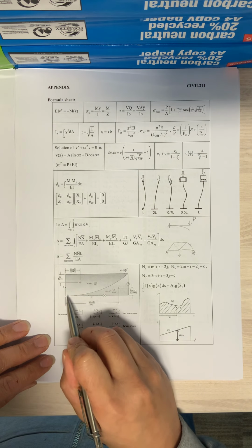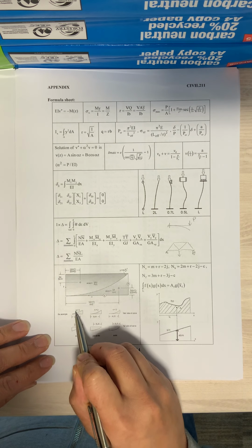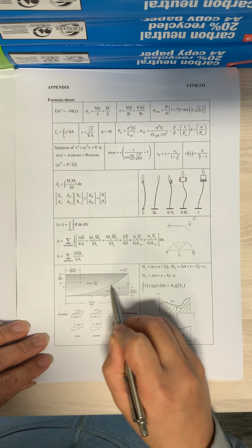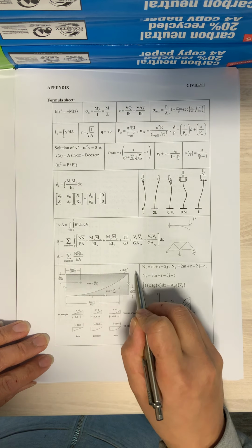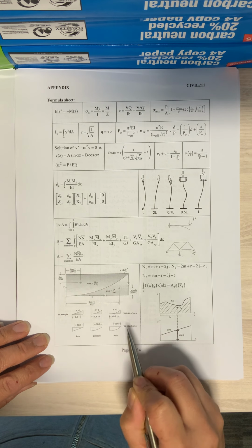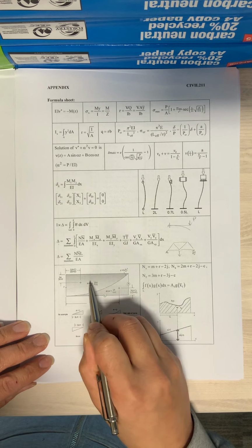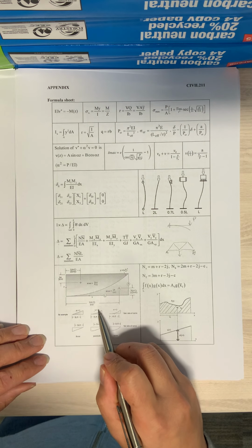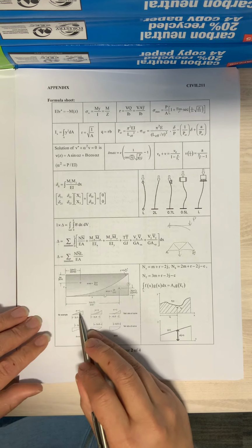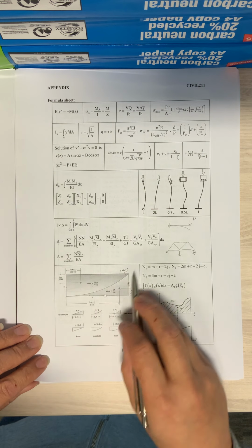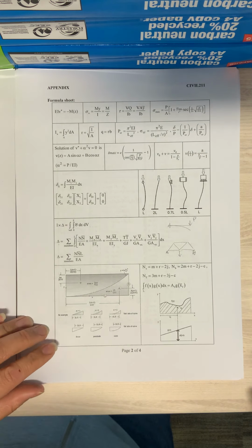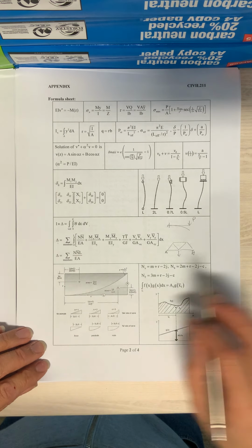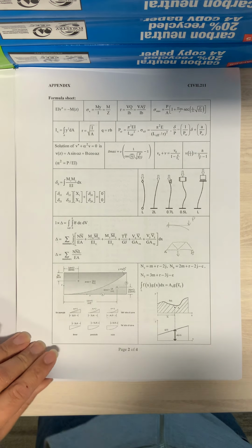So if you had a straight line passing through that, n equals 1, so linear function would be that, quadratic function may be that, and then a cubic function may be that, and then this equation here tells you where the centroid of the section is, so where the centroid of the parabola is, or the centroid of the quadratic function. So we'll talk about this one later on, but this can be used in the so-called graphical method for multiplying two bending moment functions together, for example.